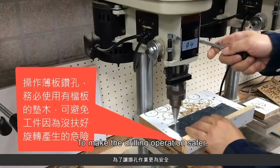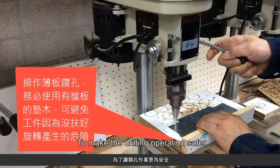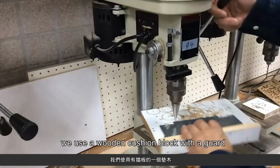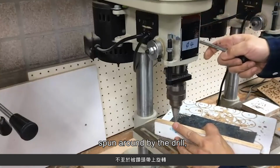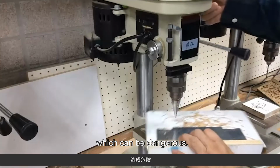To make the drilling operation safer, we use a wooden cushion block with a guard to prevent the material from being spun around by the drill, which can be dangerous.